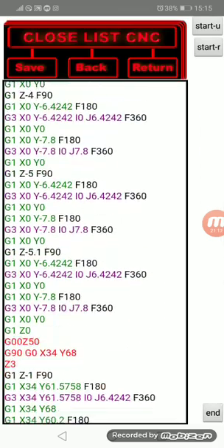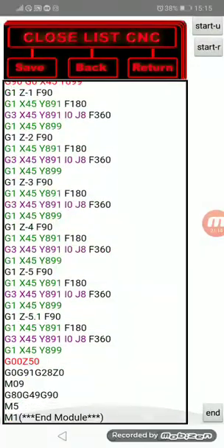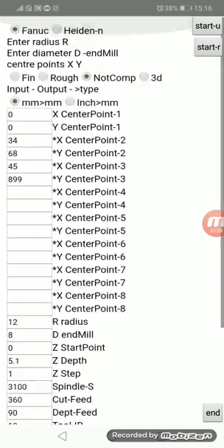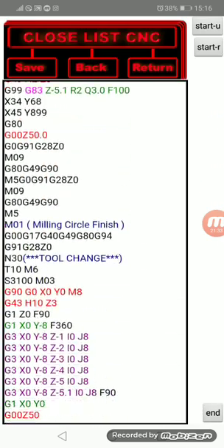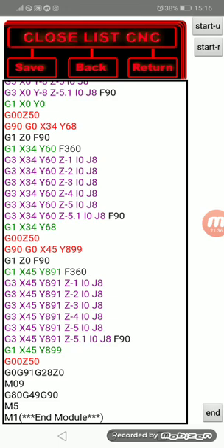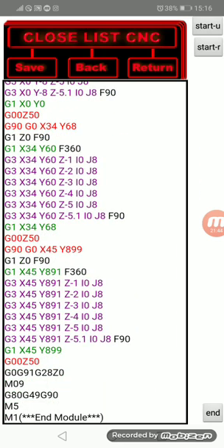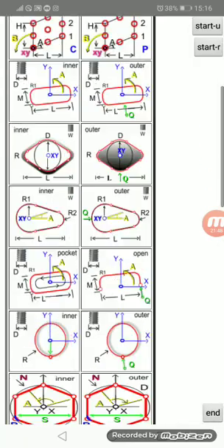And then processing without radius compensation. The same, rough milling and then finish milling. There are milling cutters which don't have mill radius. That's why it's convenient to use this function without compensation. And the third function is 3D processing. It's a finish processing along the 3 axes. It's also convenient. And the quality of holes is better and higher. Moving on.